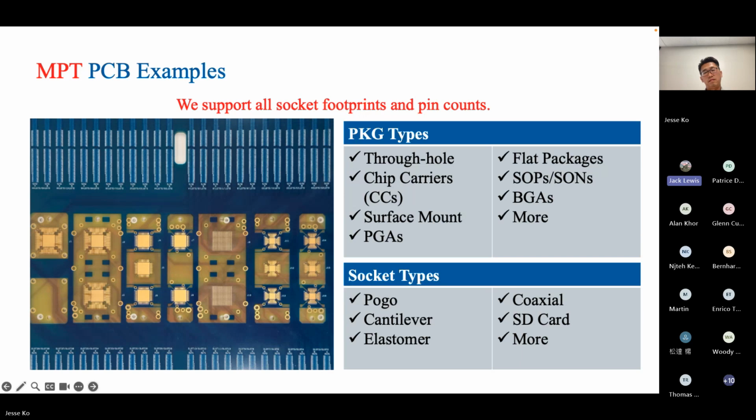Typically we use machined metal devices, plated devices with gold plating or solid silver. How do you match solder alloy? We've got lots of data that shows strong correlation between what using silver looks like and a solder ball. Typical solder ball, they're very similar, but from a plating perspective on the Regulus, we can do most any kind of plating. If you want to use a particular plating material, we can use real solder balls too. We plate Regulus, basically a shorted, balled device, with whatever kind of plating or ball, SAC 305 ball, you name it, right? So it's up to you what kind of surrogate or shorting device you want, or you can use your live packages.